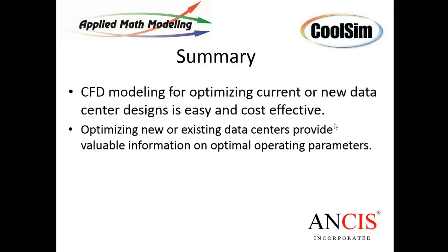The question is, how is the airflow being measured? We're not measuring it. We're modeling it. If you know the inlet of the air coming into the room and its flow rate, and you know the rack and its consumption of air, you can calculate everything in the room through CFD. That's what CFD does. Now, where sensors come in and where sensors are important is validating the model. So you run a CFD and you compare it against the values that are measured by the sensors to see if the CFD calculation is predicting what you're measuring.